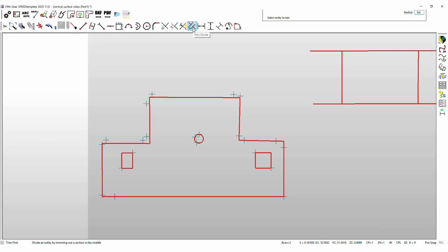This one's great for, you saw this in the farm sync video, or when you're cutting out a range manually or something like that. Simply click the trim divide tool, then click the piece that should be gone, which is the middle of this here, in between its two barriers, the left and the right, or the right and the left, whichever way you clicked. This between here and there. You can see it's now divided out the pieces, and you can see I would have a range break here.